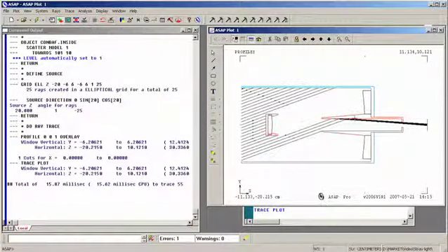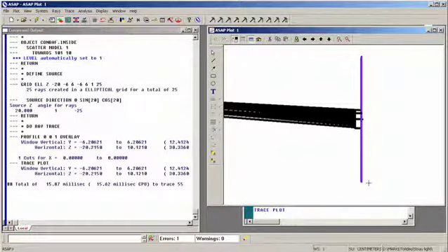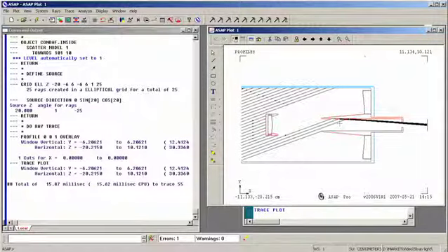Now we see a very different story. Before we had 10,000 scattered rays, none of which made it to the detector. Now we have 30 scattered rays, 10 from each of the incident rays that we see on the interconical baffle, all of them making it to the detector. So our ray trace is much, much more efficient. ASAP is handling all of the numerical values so that we get the right number.